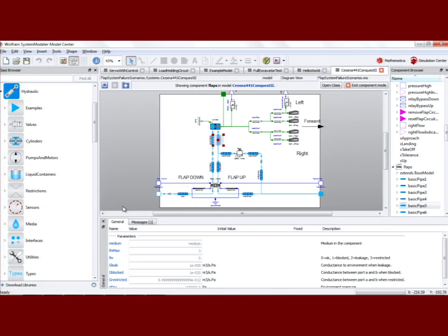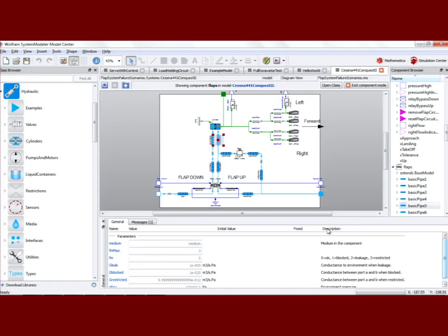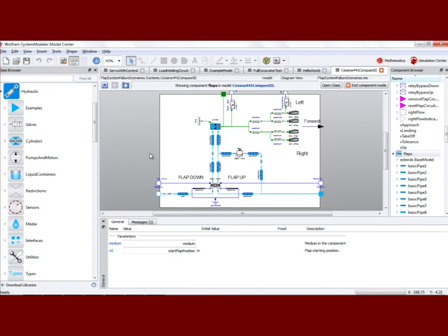It's much easier nowadays to find the right parameters in your model, because in the model nowadays there are specific tabs where the parameters are better sorted. And here you can find that this pipe has different things like the leakage. You can set parameter for that. You can set the parameter for the environment, pressure, etc., etc. And it doesn't list actually the diameter. Should do. There is a diameter for it that you can set, and as soon as it's a parameter, you can of course set it then in Mathematica and set up an optimization problem in Mathematica to find the combination which is the best fit to whatever goal you have. There's good examples on the web page for that. I can point you out to those.